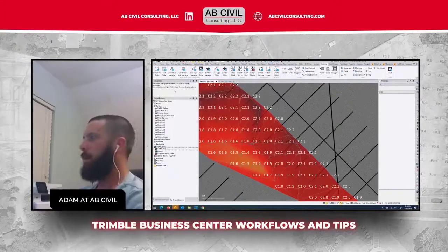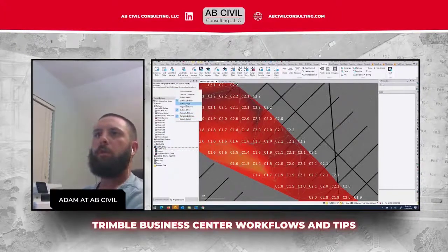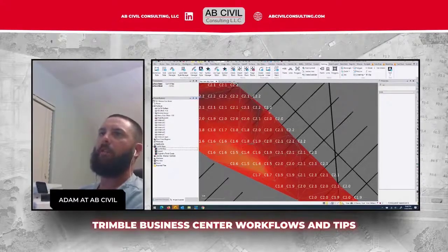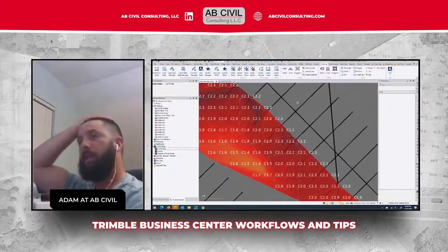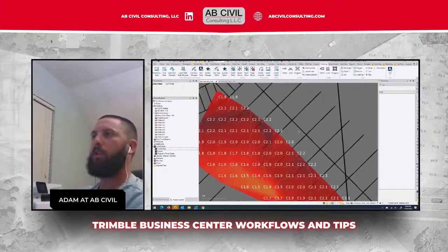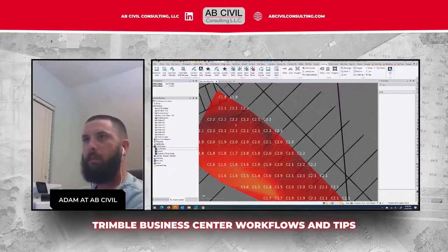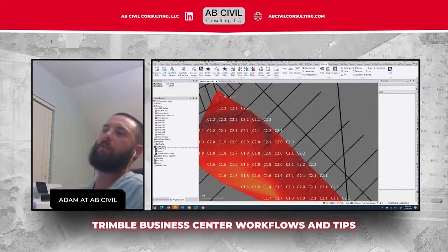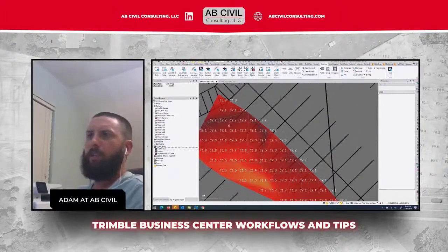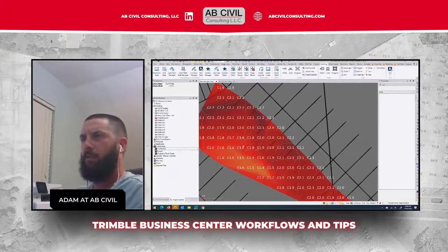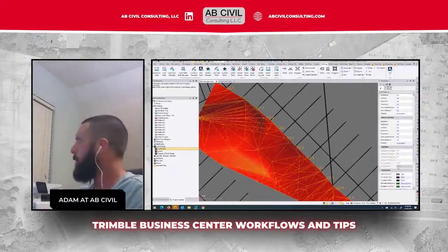If you go back up to the coordinate scroll, let's see, surface name. Now it will tell you cut fill map is the name of the surface that it's scrolling. So when my cursor's outside of the surface, it doesn't display anything. But when it gets into the surface, it's telling me to the thousandth what the cut fill was. So it's actually nice because this is a really tight grid, because it's a small cut fill map.